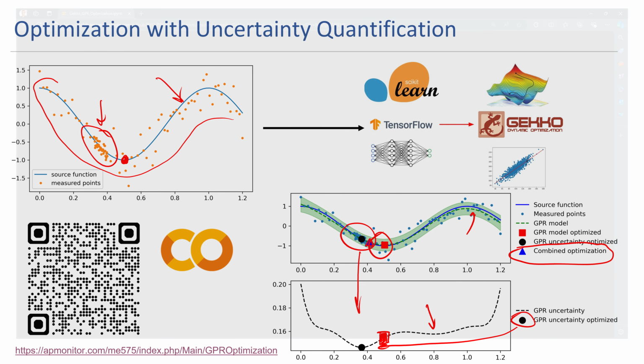Okay, we also have dynamic simulation of this continuously stirred tank reactor. Assume liquid full and first order kinetics. Use Python Gekko for the simulation. So it lists the assumptions. It shows the equations it's going to use with species and energy balances. It defines some constants that you could change, and then the differential equations for the simulation as well. So it does a fairly good job just based off that image and a short description of what I'm looking at for it to develop.